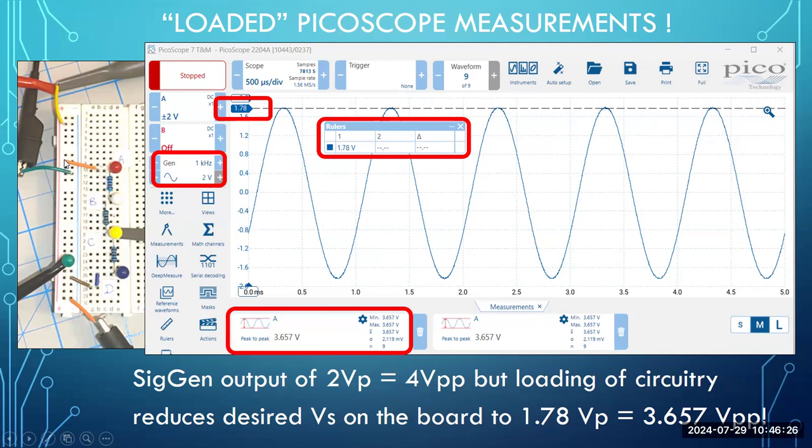The orange jumper is taking current from the red rail to the first resistor, making a connection from the red rail to the resistor. Follow these resistors down to this blue jumper and brown jumper to the negative rail. So I now have a completed circuit. Electricity is now flowing from the power rails through the sequence of 3 resistors. By having this sequence of 3 resistors loading onto the power rails, my voltage now at the peak sags a little bit. Instead of the 1.9 something volt peak that I had previously, I now have a 1.78. It has dropped a little.